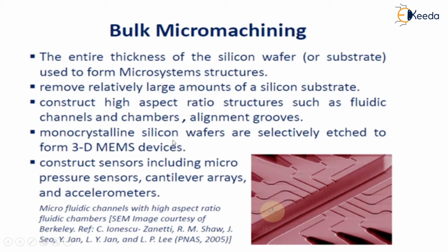Monocrystalline silicon wafers are selectively etched to form 3D MEMS devices and construct sensors including micro-pressure sensors, cantilever arrays, and accelerometers. Microfluidic channels with high aspect ratio fluidic chambers, in SEM, are shown in this figure.